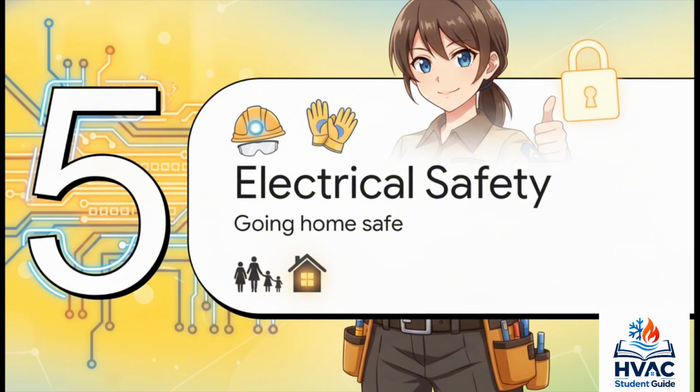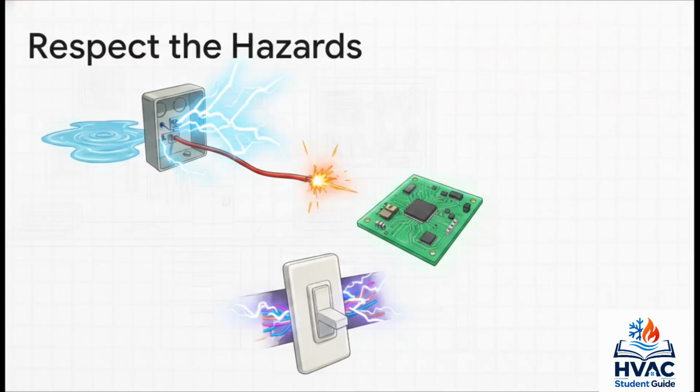Which brings us to our final stop, Section 5, Electrical Safety Rules. Look, all this diagnostic power means absolutely nothing if you don't go home safe at the end of the day. You've got to respect the hazards. Never perform energized work just because the scenario makes it sound like a routine thing. Shock paths and wet conditions drastically increase your danger out there. And remember, even a low voltage 24-volt line can spark, destroy a very expensive control board, or shock you into a startle reaction that causes a bigger injury. Oh, and simply turning a wall switch to off, that is never proof a circuit is safe.